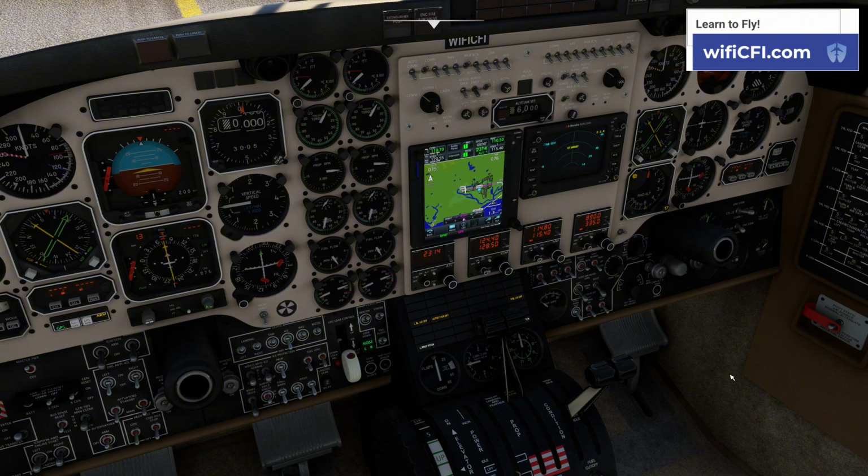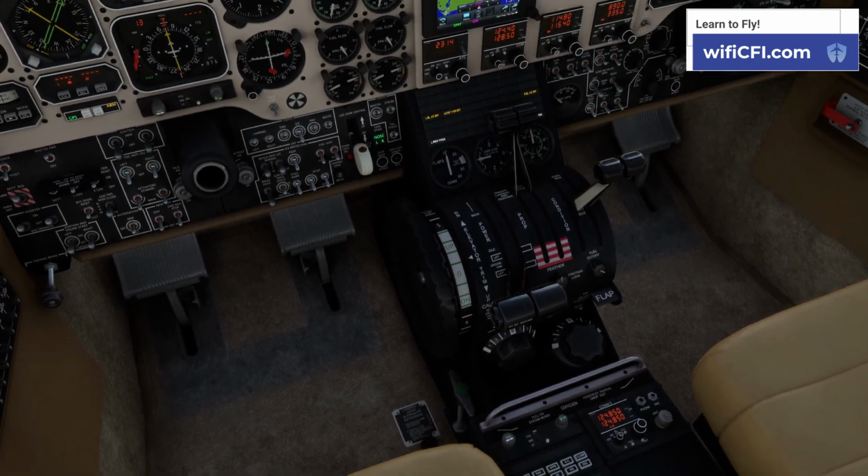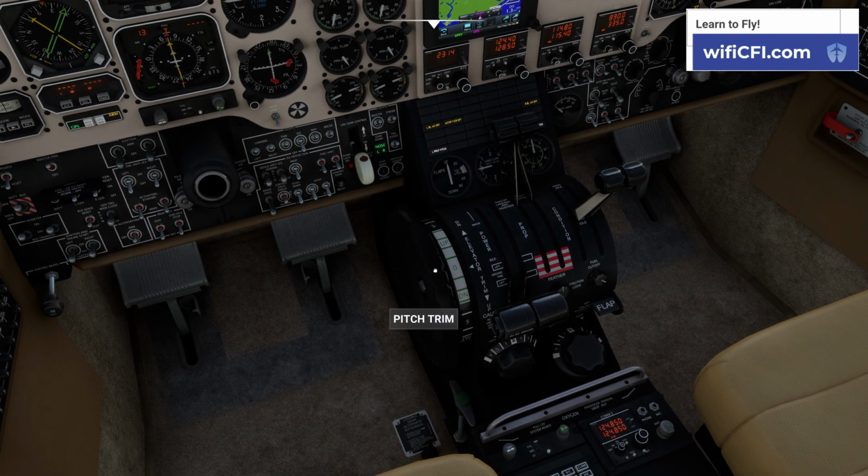Flight controls and electric trim, we would check. With the yoke, it's kind of pointless to do it in the simulator, but we would check it in real life. Here we got our trim, so we're going to set everything to neutral for takeoff. Neutral's on the trim. Flaps checked and set. Let's make sure our flaps work. We'll extend it down. You can see we extend it there. Comes down to approach. Extend it again. Come all the way down. Obviously, you would also look out the window as well to see those flaps coming up and down. Autopilot checked. We're not really going to check that here in the sim just because it doesn't really work that good. Pressurization test we will do.